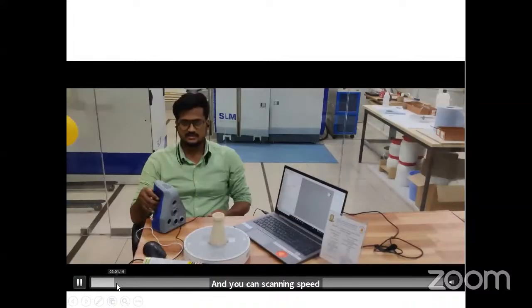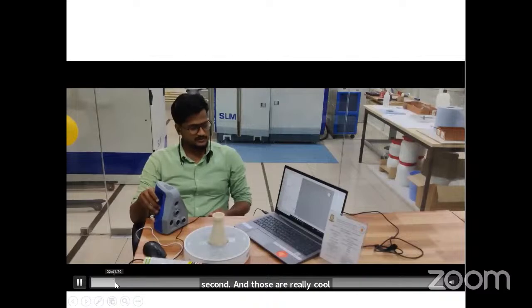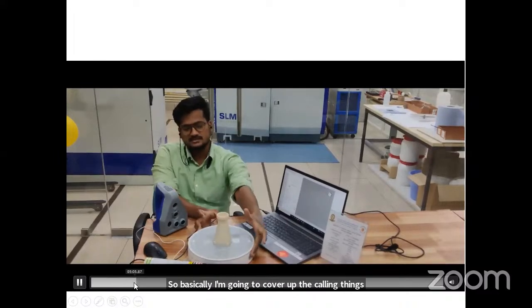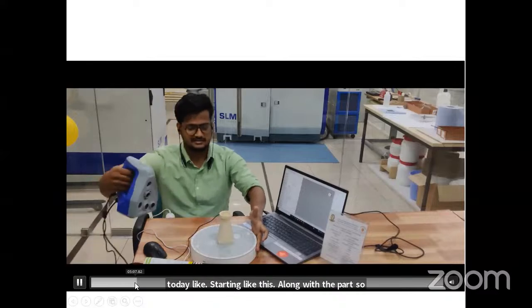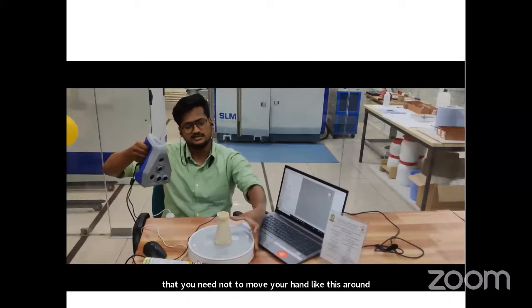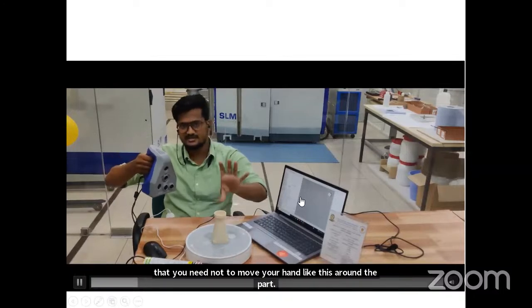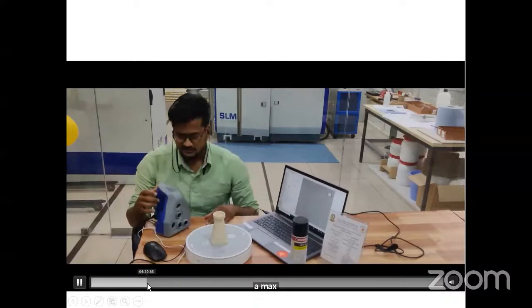Accuracy is around 0.05, and the software is Artec Studio. Today I'm going to cover the following things. We start with the part on a turntable, so that you need not move your hand around the part. You will be in a constant position, and the part will rotate, so you can scan with minimum effort.